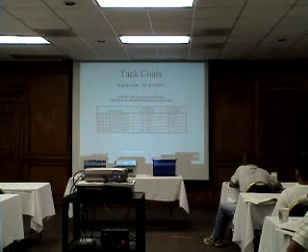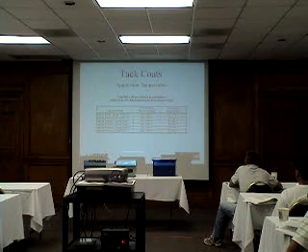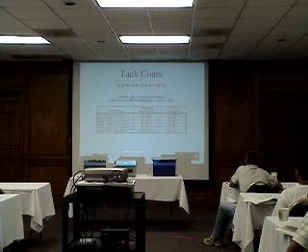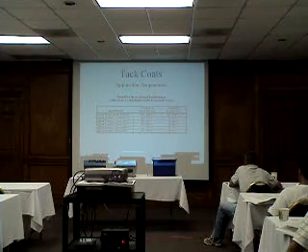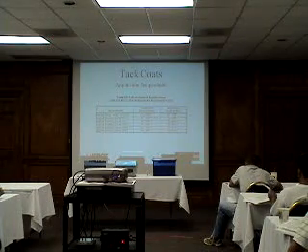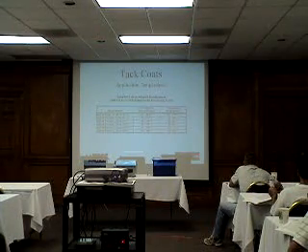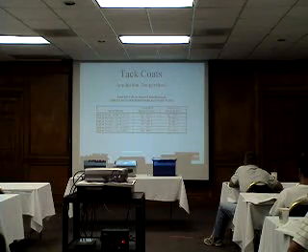Because you look, the first one here is what? That's PG 64-22. That's the actual binder that we put into our mix. To get it so it will come through those spray nozzles, the temperature range has got to be about 400 degrees to have it hot enough. That's very, very dangerous. It's getting close to the flash point. And you don't want that stuff to flash.